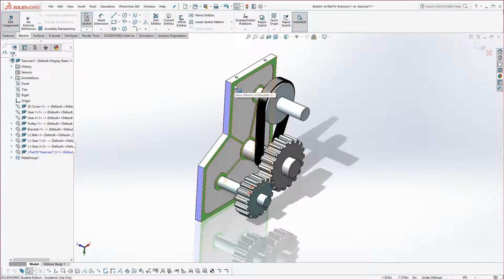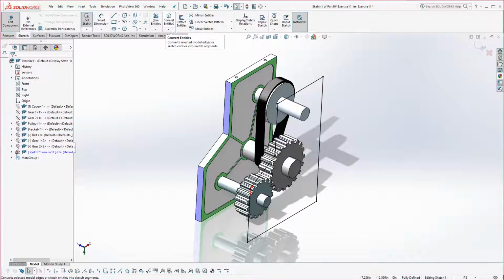So with that being said, go ahead and select now what, again, this is top-down modeling with sheet metal. So some of this, if you're just going to this video without knowing what top-down modeling is, you can watch exercise 10 and exercise 11, which goes into more detail. I just don't want to be too redundant with that. But go ahead and let's select this face, and that surface is our front plane where that origin is. So we could select this face, and we could hit Convert Entities, and it will automatically project the edges onto the surface of the new part that we dropped in, which is the front plane, I should say.